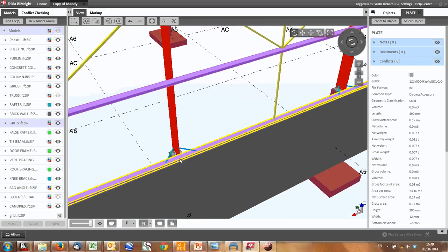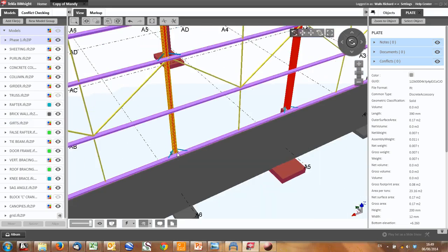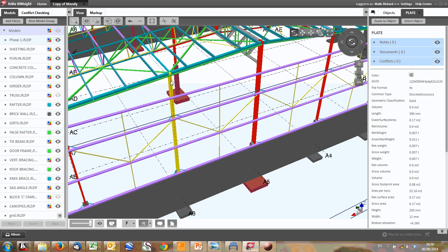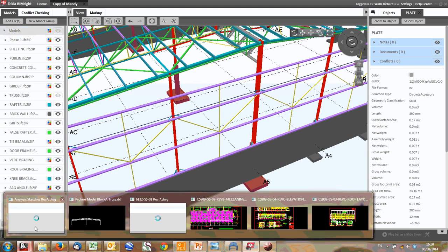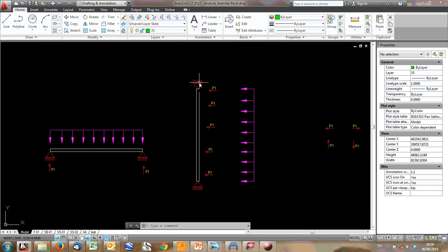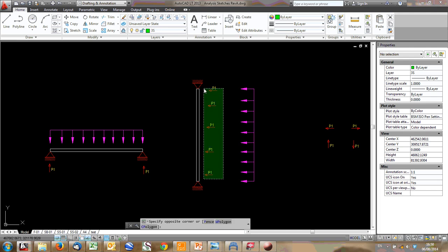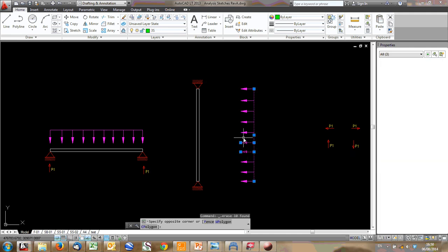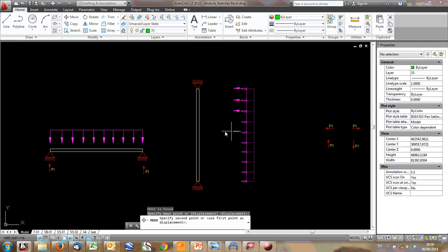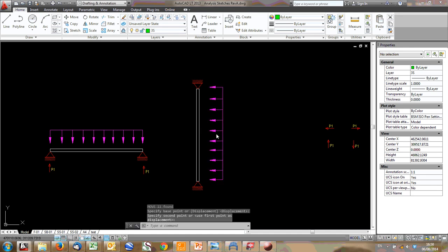This is very simple. This connection at the bottom could either be fixed or pinned. And the top, it's pretty much always pinned. So we carry our load now up or down. Once again, we get to a situation like this. We've got a simply supported column with loads. These could either be our girt loads, or we could define it as a UDL. If you want to do a quick design, this is more than sufficient, and it's even sufficient just to put a UDL most of the time.